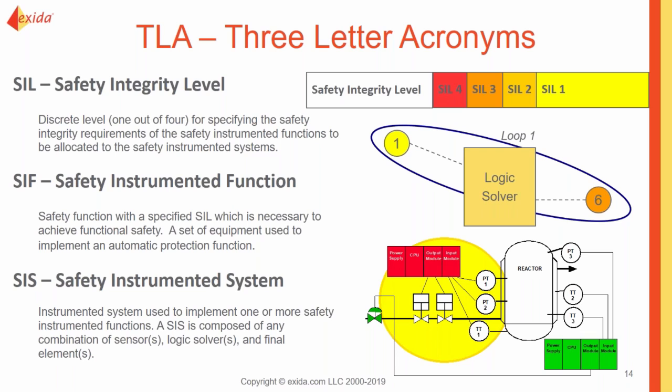So if you think about it, you have a set of equipment, a single set, maybe some sensors, a logic solver, a final element, and this set of equipment is going to look for one single hazard scenario. And that set of equipment needs to take action to bring it to a safe state.